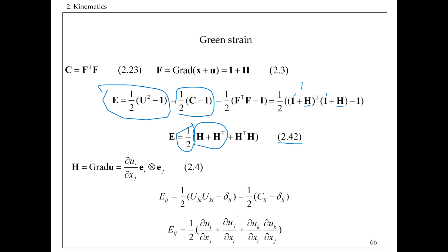As I said, the first two terms, if you recall, are exactly how in general you wrote the engineering strain before in linear elasticity. Also, these are the linear terms. With the Green strain, the difference comes when the nonlinear terms become significant and we cannot neglect them. So this is the nonlinear term. You can see that we have the first derivative, and here we have this first derivative multiplied, right? So this is a quadratic term.